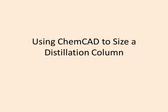This presentation will give you a step-by-step method for using ChemCAD to design distillation columns and also determine how much it would cost. Before we begin, we're going to select a shortcut column to give us preliminary design numbers to use. This is found in the palette under shortcut, and this is what we'll be adding to our spreadsheet with the ChemCAD.